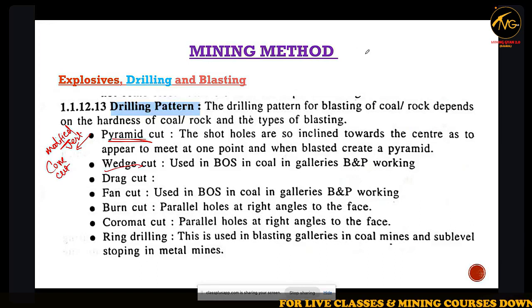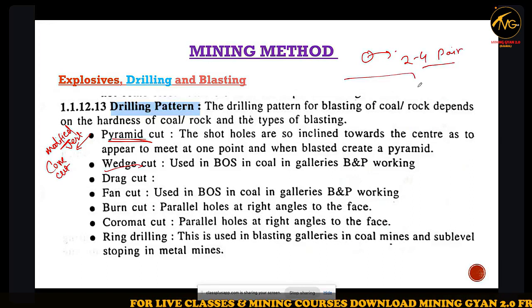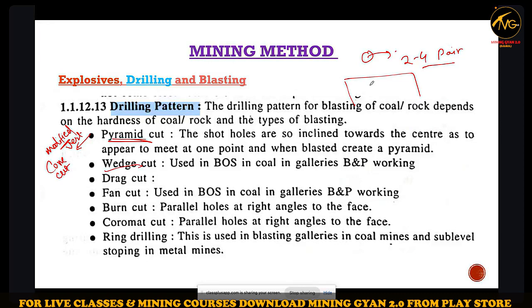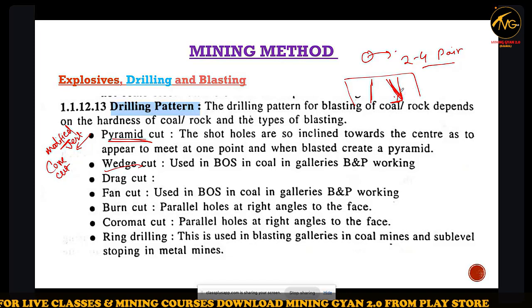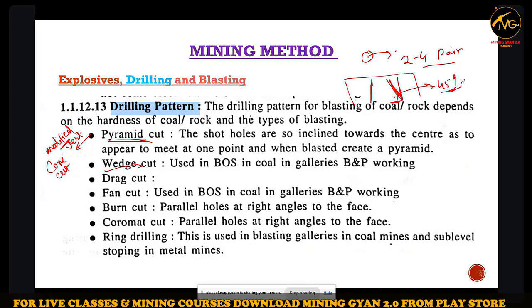So in the wedge cut, two to four pairs of holes we will drill, and the angle should not be more than 45 degrees, less than 45 degrees.